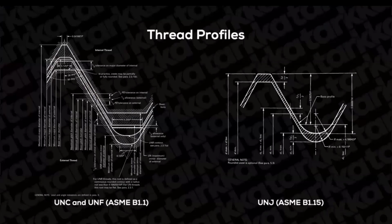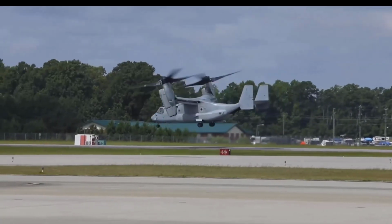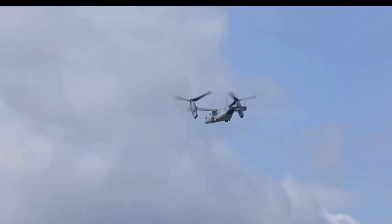A slight variation to the UNF and UNC standards is the J-type thread. Instead of the root of the external thread being a sharp V, the J thread has a prescribed root radius. The radius helps improve fatigue performance for cyclically loaded screws. You typically only see this type of thread in aerospace.